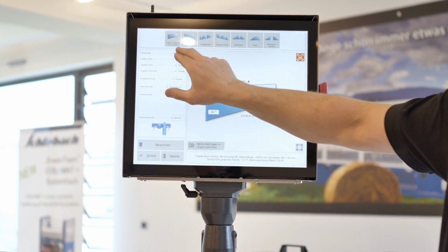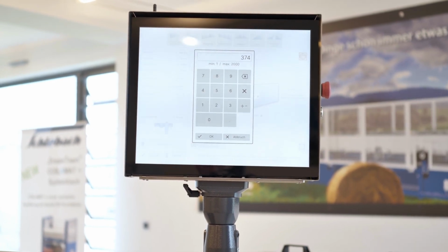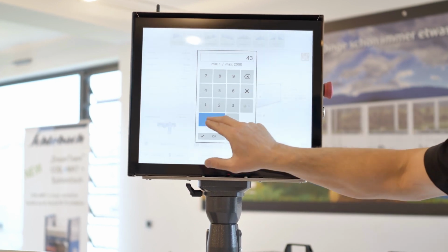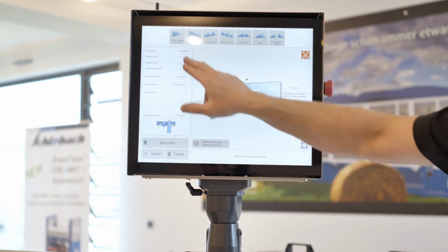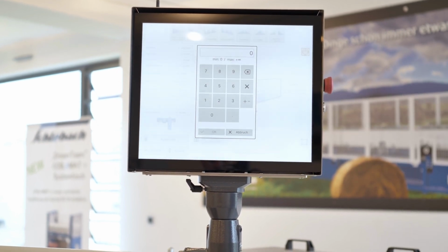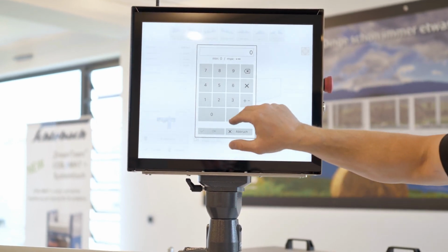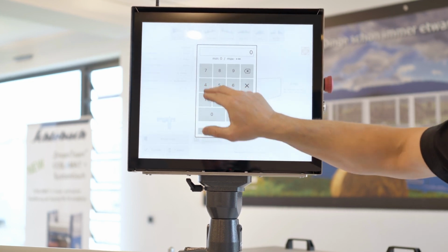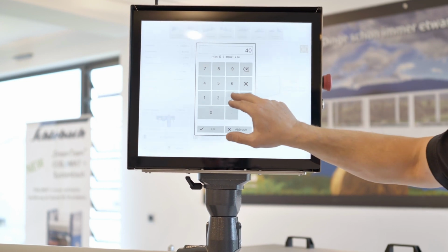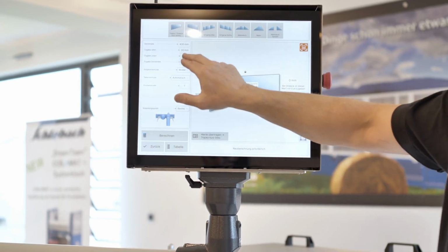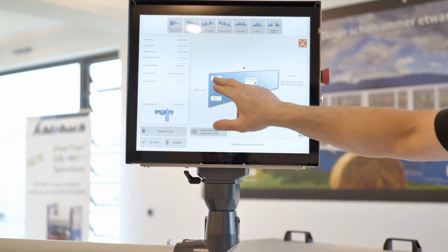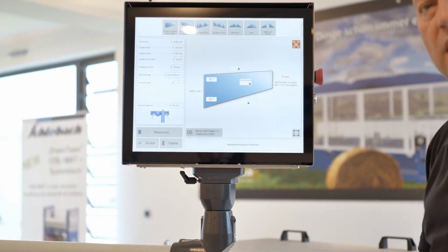Then I can also change the whole thing via the cover width. We currently have a 50 millimeter coil in, so we have a cover width of 430. If I enter that, I get the 430. I can then add allowances for the fixed connection or eave connection. In this case, it was the eave connection. So now I'll say I need 40 millimeters for that. Oh, stop, wait, at the top. There I only need 30 millimeters, and at the bottom at the eave I need 40 millimeters. Then I can calculate my dormer, as I have it now, in new construction using angles.